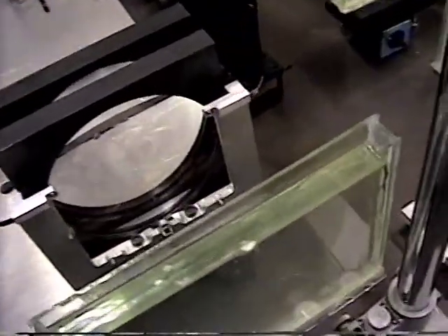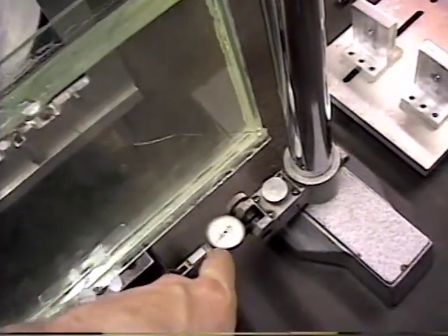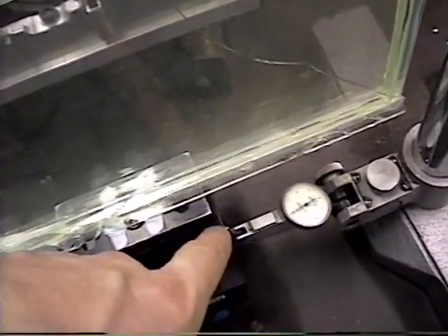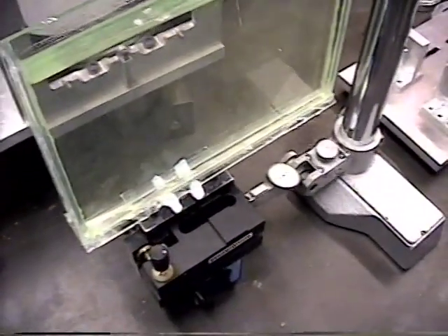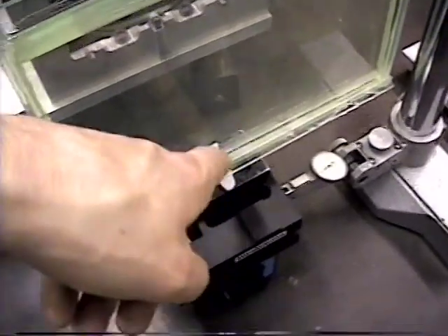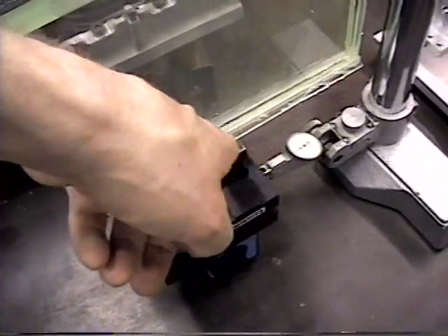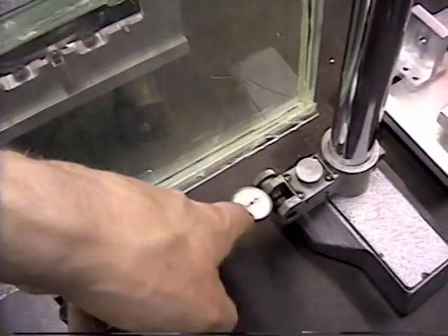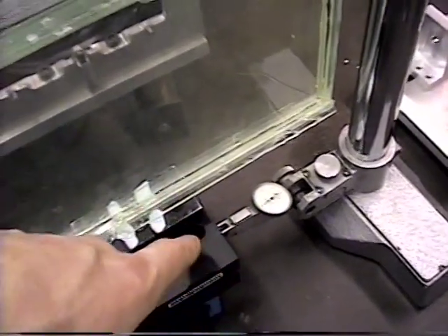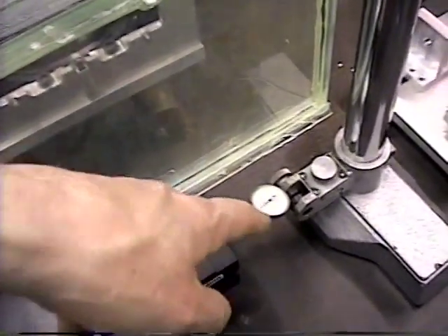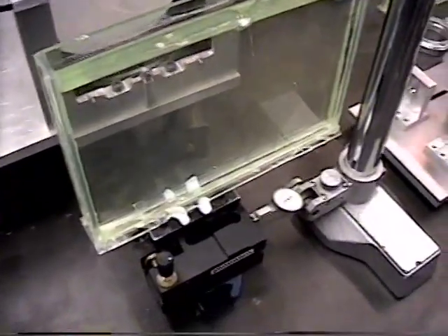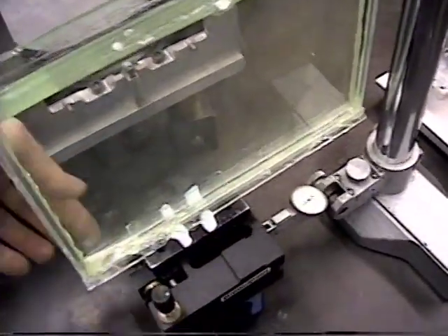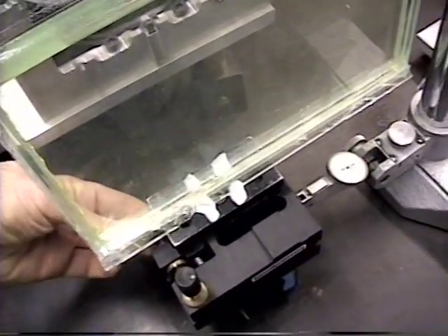But in order to do that, I had to put what I call a feeler gauge, some people call it a dial gauge, at the end of the platform, which is located a distance of 40 millimeters from the pivot of this system. So 40 millimeters means that I have to have a 200 micron displacement at this 40 millimeter distance, in order to give me a 50 micron displacement at the 10 millimeter distance. And so I set this up to displace 200 microns over 40 millimeters.